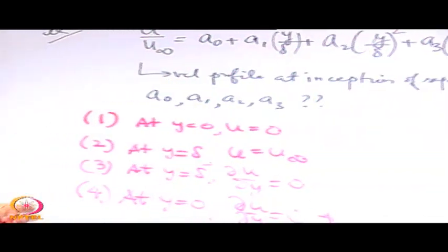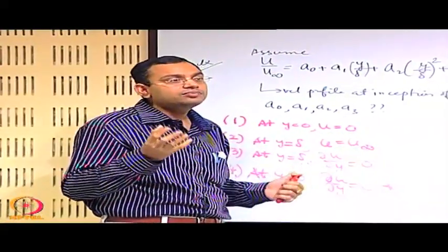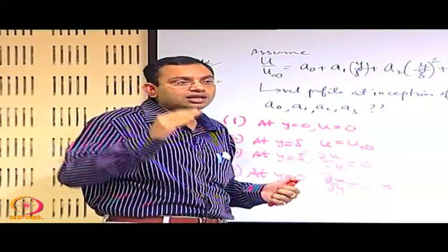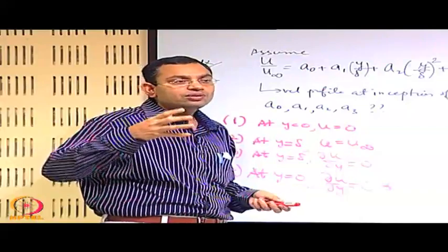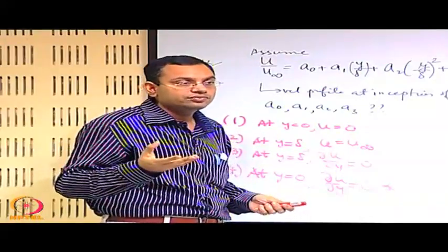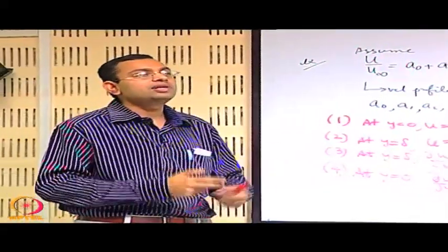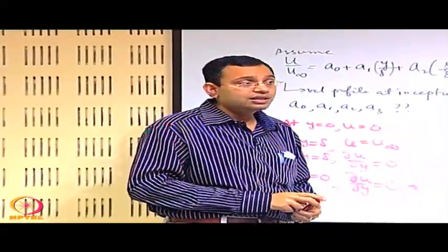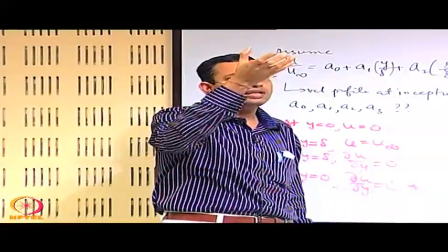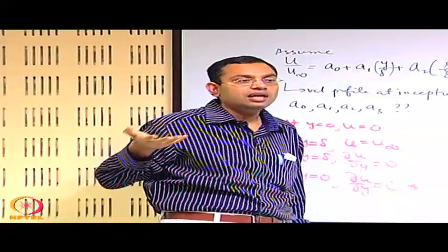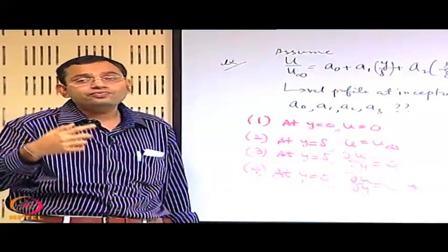Now the big question is why such a separation will occur. When the fluid is within the boundary layer it has some energy, but because of the reduction in velocity imposed by the shear effect within the boundary layer, the fluid has a tendency to get slowed down. Still it has to move forward, so what will make it move forward? One is the shear interaction with the outer layer. It takes some energy from that and tries to retain its forward movement, and if you have dp dx less than 0, that on top of it helps it.